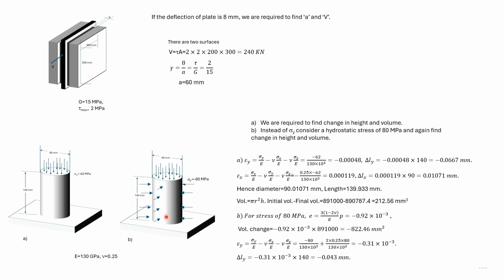To find the change in height, we have to find epsilon y. Now, to find epsilon y, we have to use all the three stresses, and we can find the value of epsilon y. Multiplying it by the length, we find the change in height.